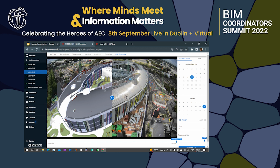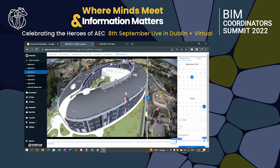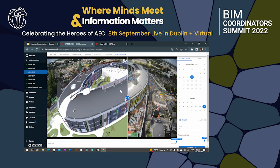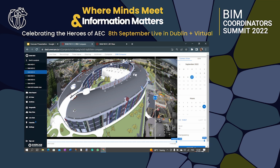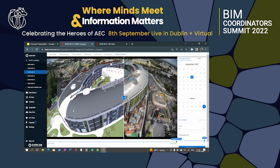We overlay them here on top of the camera live view, and the customer will be able to drag the handle and compare what's happening on site versus what has been designed on the BIM model, to track the progress, to track the quality as well, to know if I'm installing the right type of window, roof, door, and so on. Here in the bottom, I have the 4D timeline.